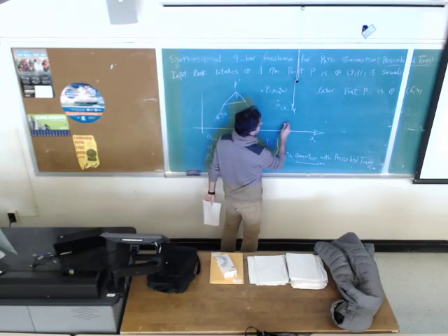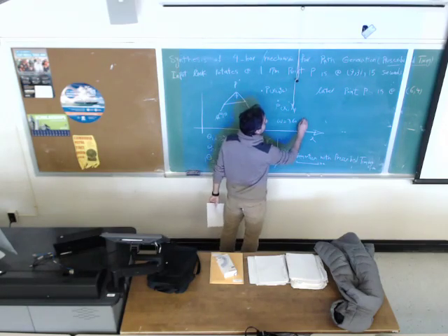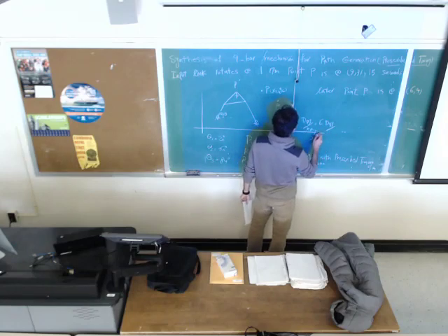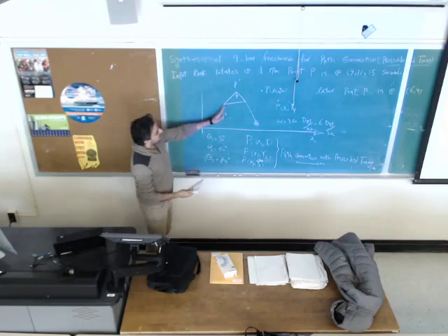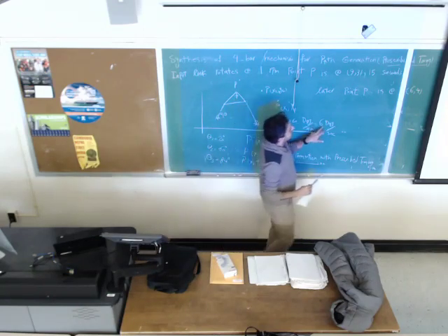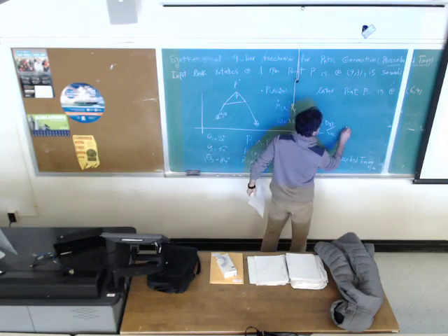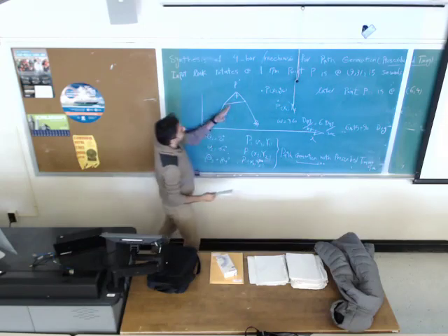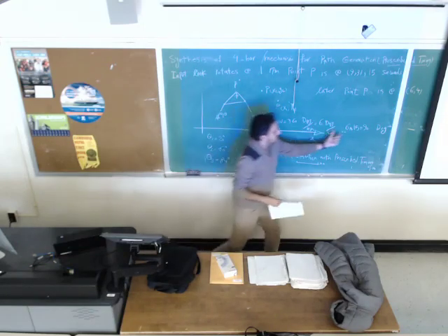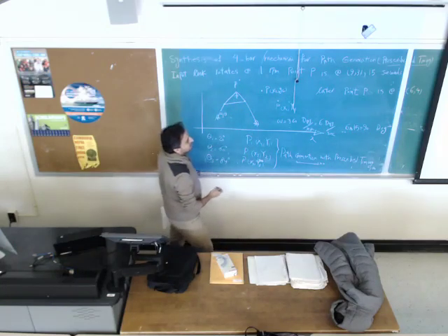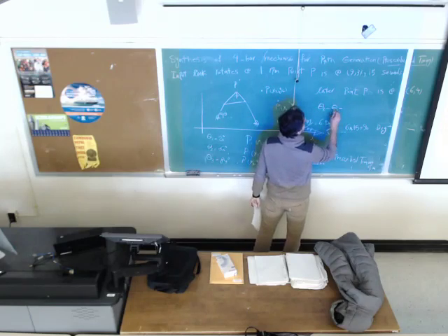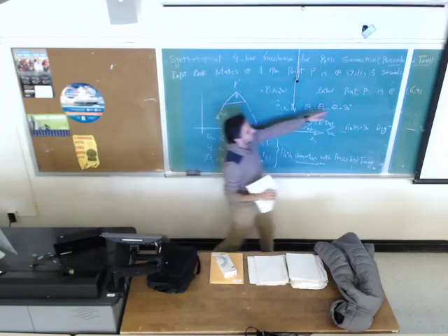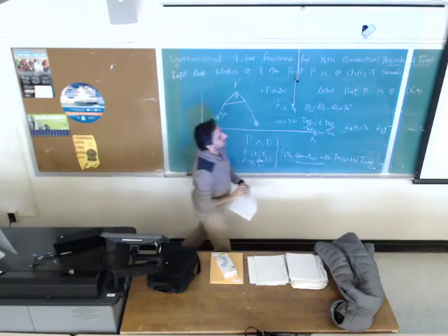It's 1 revolution per minute, meaning omega is 360 degrees per minute or 6 degrees per second. Every second, this input link is going to move by 6 degrees. 6 degrees times 15 seconds, 6 times 15 is going to be 90 degrees. So when you are moving from the first precision point to the second precision point, the input link is going to cover 90 degrees. It means theta 2 minus theta 1, which is theta 1,2, is 90 degrees. So this timing is important. You would like point P 15 seconds later to be at 6, 4.